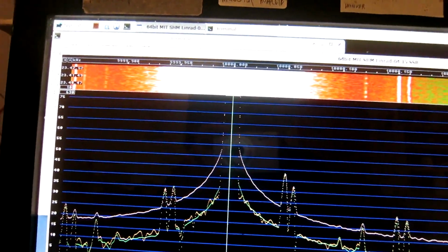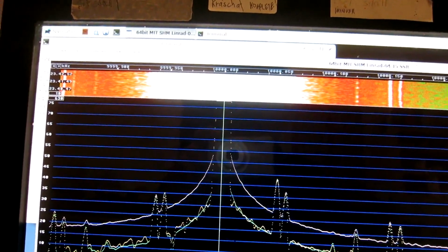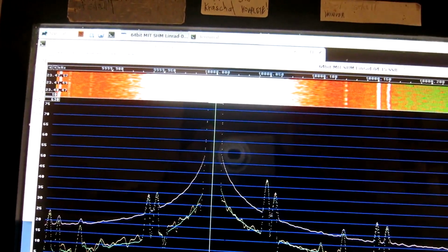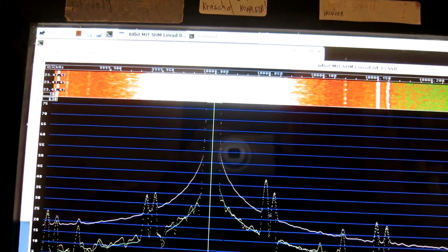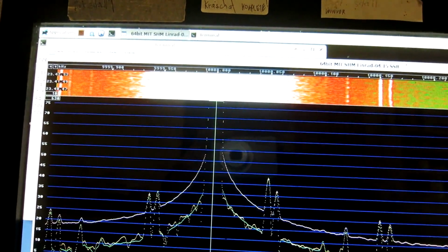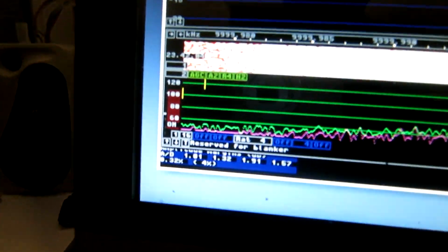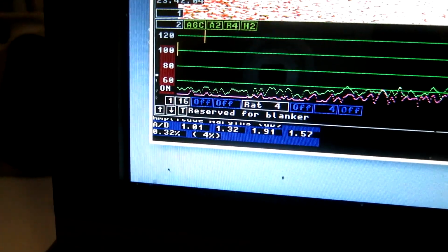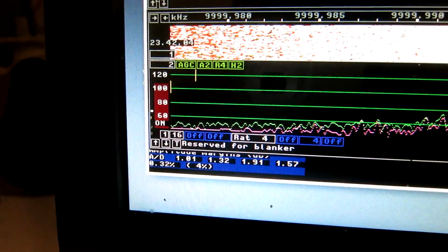Now the selective amplifier has been running for quite some time with 4 dB more input power to compensate for the loss of gain. That gives approximately the same input level, 1 dB from AD saturation, that I had before.